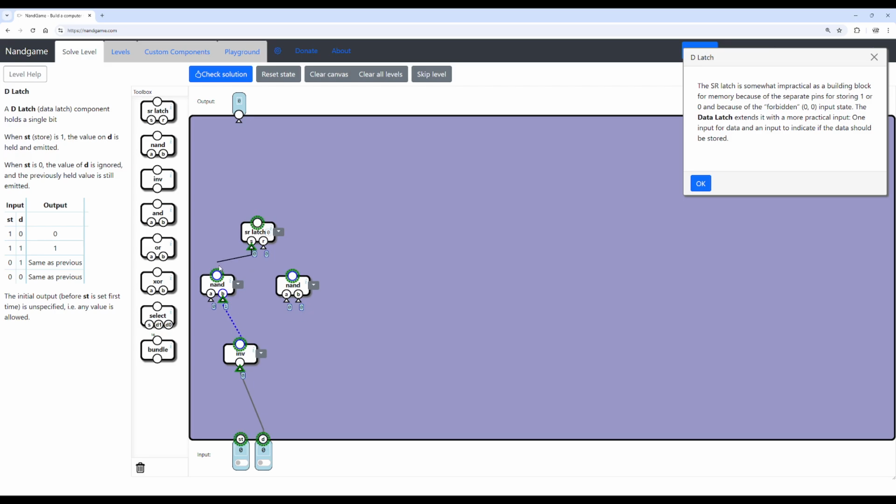And by the way, this NAND gate is the set because we're setting data, and you'll see why we do an invert later. But what we're going to do is this store bit will go to this NAND gate and also this NAND gate. And then finally, data will also go to this NAND gate. So again, this complementary behavior. What we're going to do is when we set this 1 and D is 0, output should be 0. When we set both to be 1, you can see it's 1.